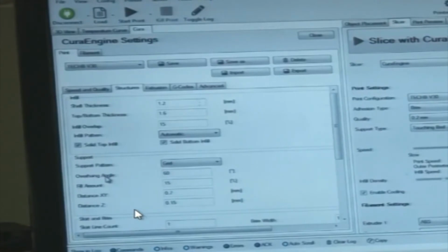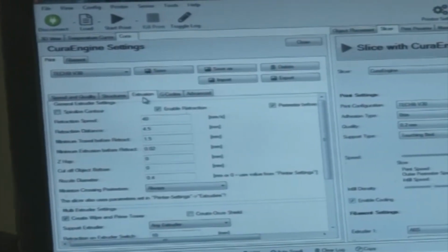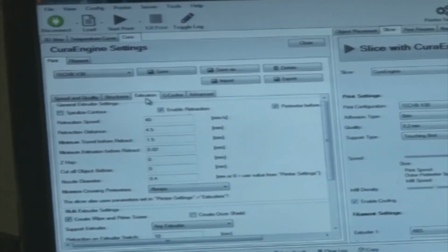So this overhang angle is 60 degrees, and next, we need to see whether there is anything overhanging in the CAD model. In the CAD model, if there is an overhang, then we need to put this angle. So if anything is overhung, then we need to provide this support, and only then can we proceed further. So then the overhang angle has to be decided.